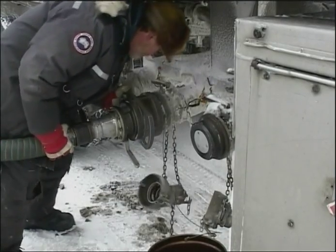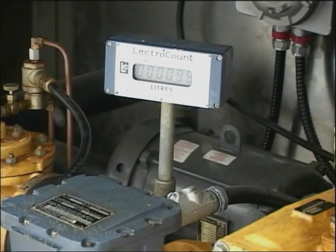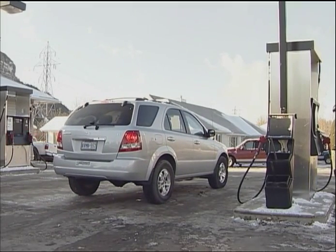For safety reasons, never dispense gas while your storage tanks are being refueled. If you have to leave the pump unattended at some time during the day, it is important to lock the pump. You do this for safety and to prevent theft. At the end of the workday, close the pump area by reversing the opening procedures.